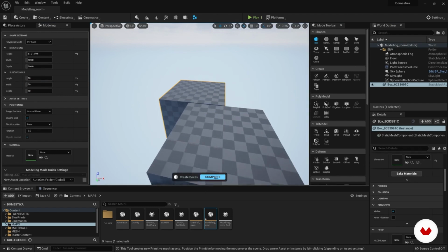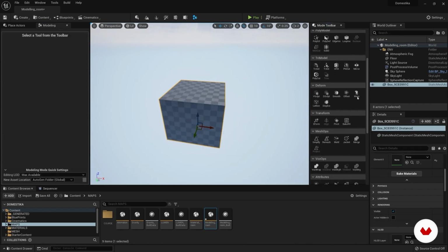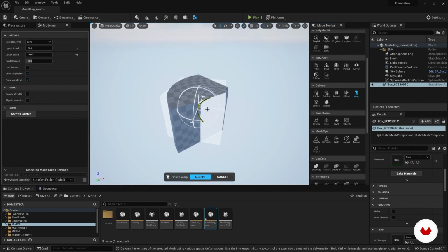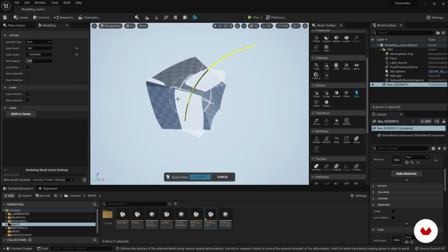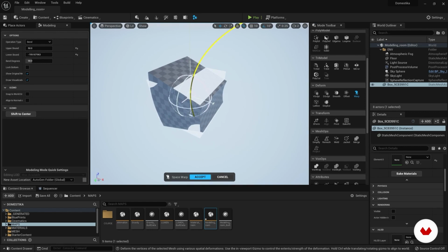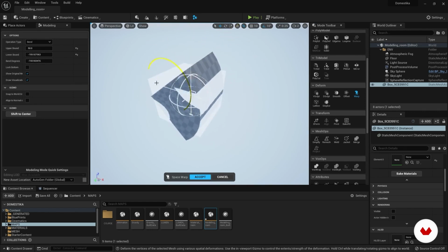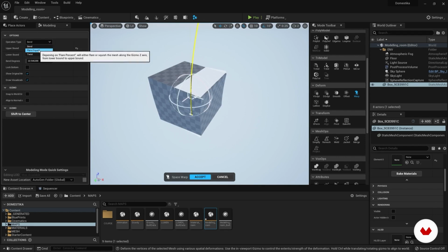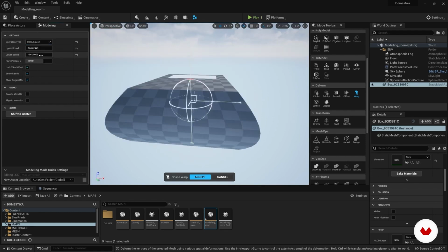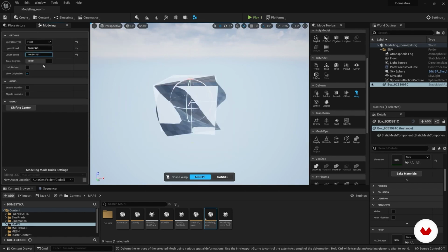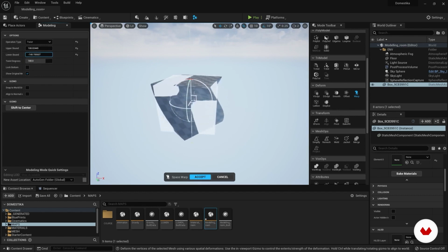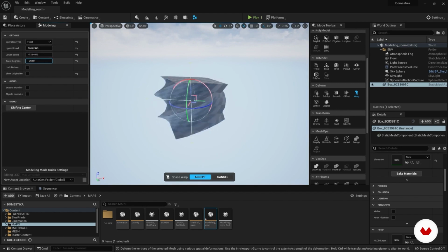A deformer, which has nothing to do with sculpting, but it is certainly very useful, is warp. We can use it with operation type bend. It is just a deformer that takes care of folding a bend, as some other software would call it. Flare and squish is a kind of squash and stretch. And twist. I took off Show Original Mesh because it bothered us. It is an excellent deformer which will often come in handy.